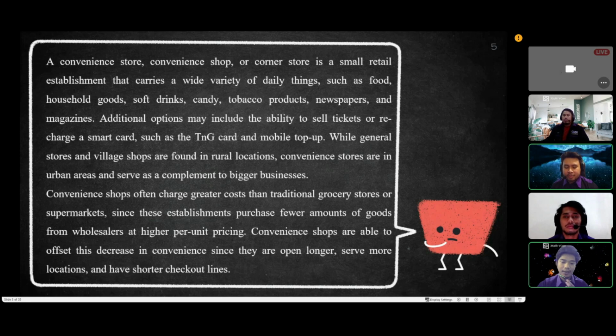The LED bulb is used because it has a better long-lasting duration and it is cost effective, due to the LED bulb having lower wattage usage than the fluorescent lamp. And next for this project, there are some parts that need to be changed such as the water closet and others. For the sanitary system, the water closet that was initially used is the Indian style water closet, which needs to be changed to the European style water closet.